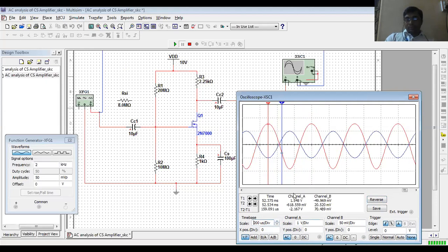We have to keep the scale clearly to observe the waveform. In a similar fashion, at the same time, this channel, we have applied the 50 millivolts, so we have to keep the scale at 50 millivolt per division, and this would be the amplified channel A, that will be some higher value of the voltage, maybe 1 volt here. Keep the signal on the AC position.